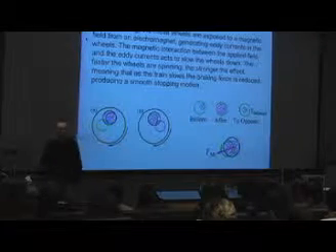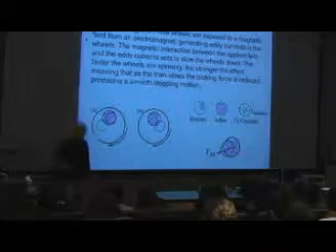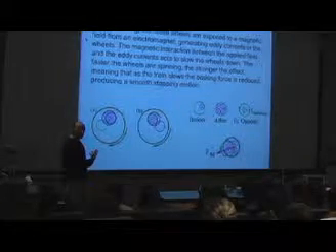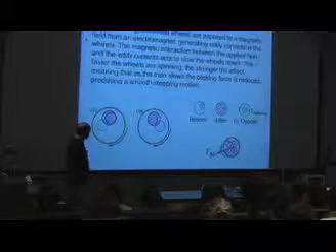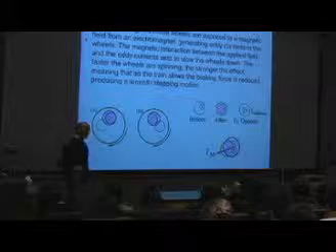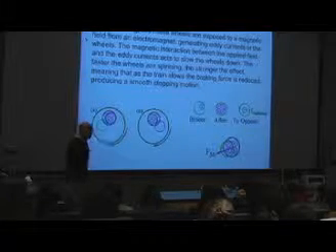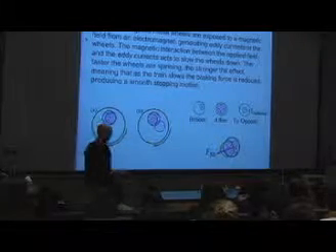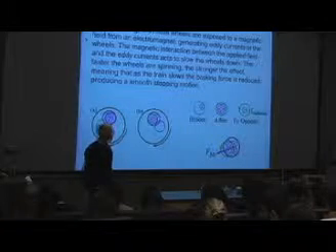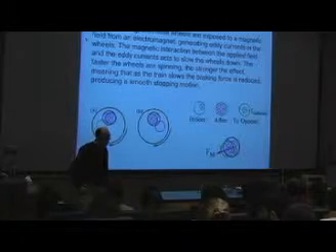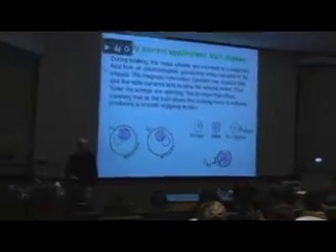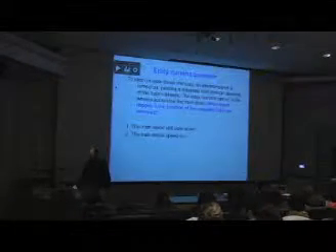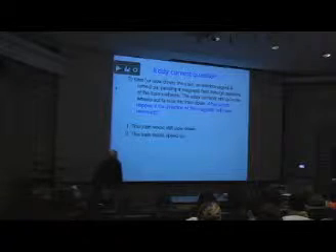Okay? And the faster the wheel is spinning, the bigger the force is, because the bigger the current is, the faster the rate of change of flux. So you get this really nice smooth braking motion. As the train slows down, the force gradually decreases till you come to a nice stop. Okay, so that's the basics of how train brakes work.